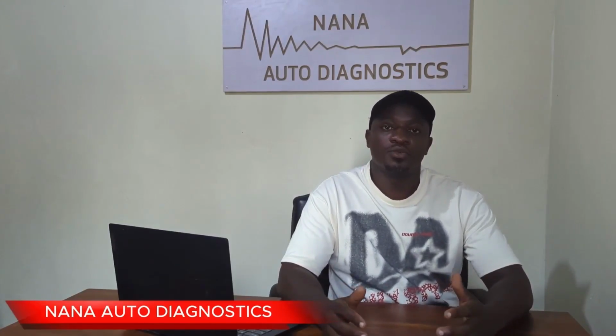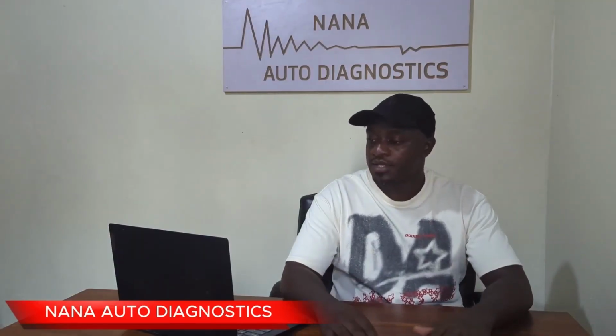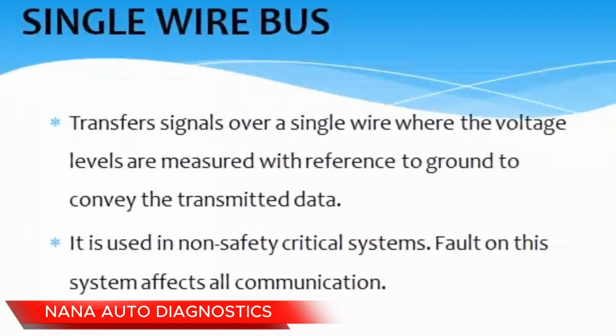When we are talking about communication networks, these networks usually employ two types of buses. We have a single wire bus communication network. We also have a differential bus network, which uses a twisted pair of wires. A single wire bus network transfers signal over a single wire, where the voltage levels are measured with reference to ground to convey the transmitted data.